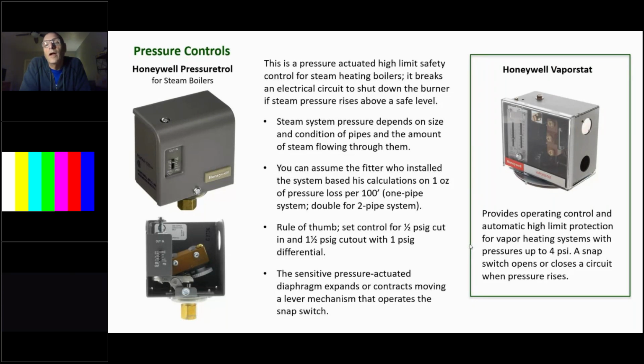And because of failure throughout the years, people have gone back and put standard radiator valves on. So the way to try and make that system work is to close off all of the new style radiator valves, and then fire the system, and then just go back and slowly crack each one. You probably won't be opening them very much more than maybe a quarter turn in order to try and balance that system.